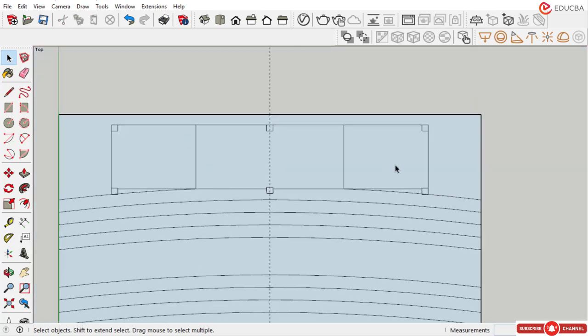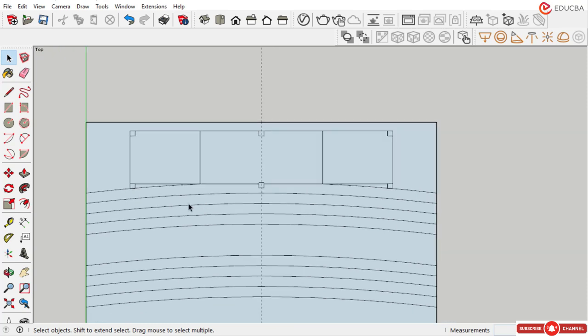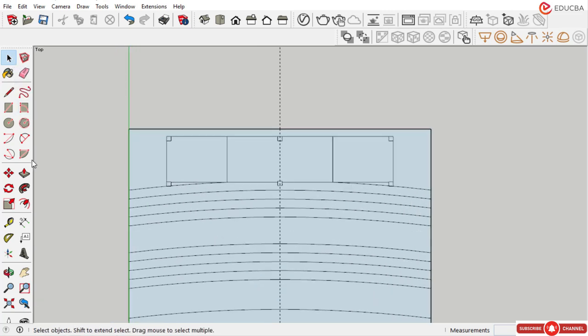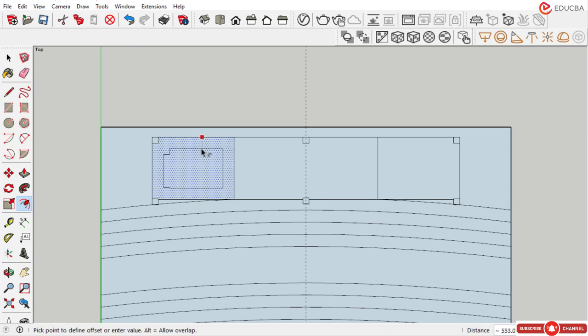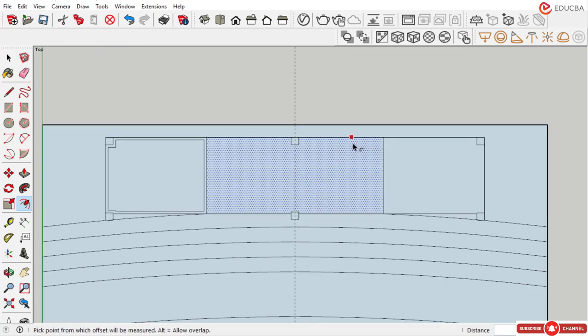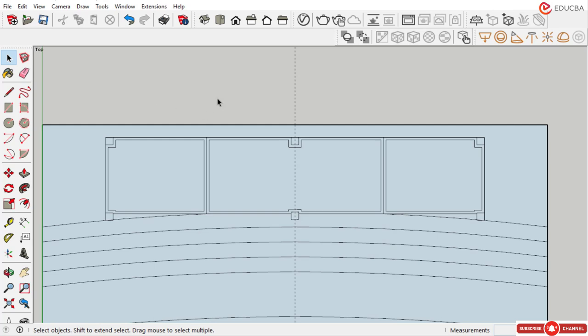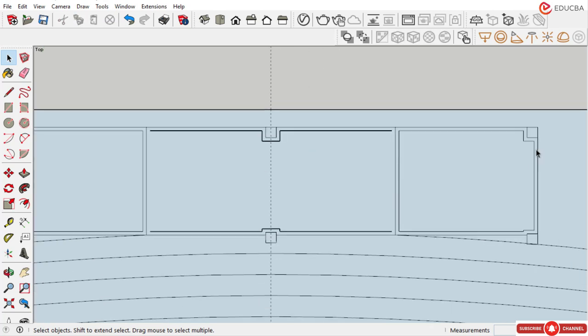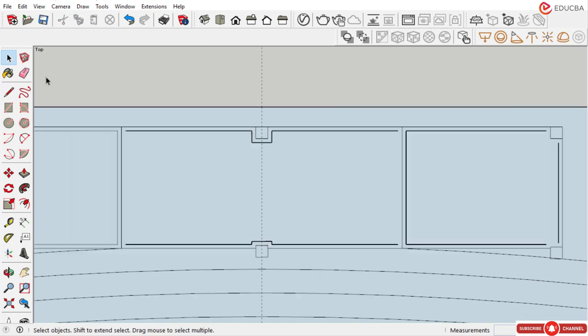So now our cabins and sitting arrangement is the rectangle type area, whereas our steps arrangement is the curve area. So we can easily offset for the wall for the cabin here to here, 100 mm offset. A 4-inch wall must be there, from here 100 mm, and from here 100 mm. So this is the wall. Now erase this as well as this line and extend this further.